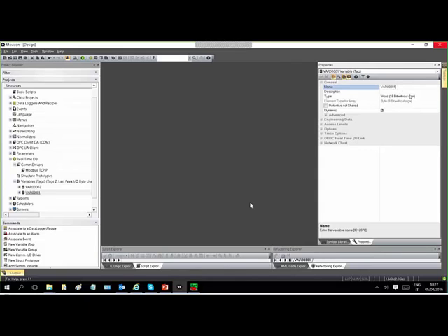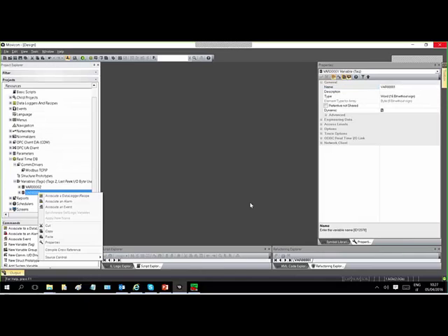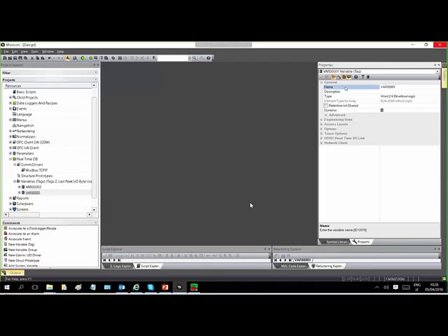Tag name, you can replace the tag name from here. Remember that if you replace a tag name, here you will keep between brackets the old name. I suggest to apply the new name in all the resources when you change the name, because you do not change the tag only locally, but maybe the tag is used in a different context. So if you apply the new name, you will apply the name in all the resources of the project.